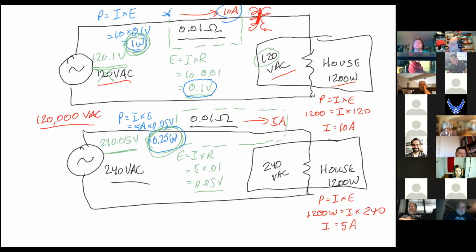So we deliver the voltage to that transformer, which is very, very efficient at 120,000 volts. And the power is conserved, which basically means that we have dropped our current by a factor of 1,000, which means we've dropped our power dissipation by a factor of 1,000,000, which is really good because instead of heating up the wires, we can actually sell the power, which is exactly what we want to do.